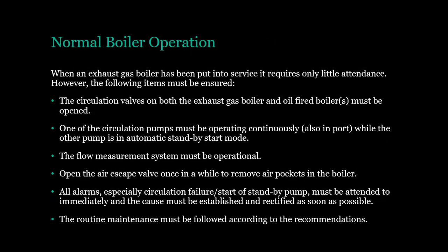Normal boiler operation. When an exhaust gas boiler has been put into service, it requires only little attendance. However, the following items must be ensured. The circulation valves on both the exhaust gas boiler and oil-fired boilers must be opened. One of the circulation pumps must be operating continuously, also in port, while the other pump is in automatic standby start mode. The flow measurement system must be operational.